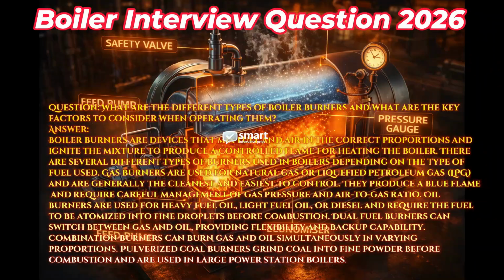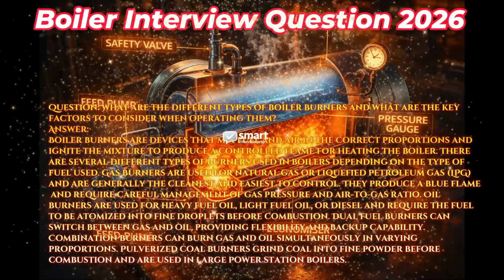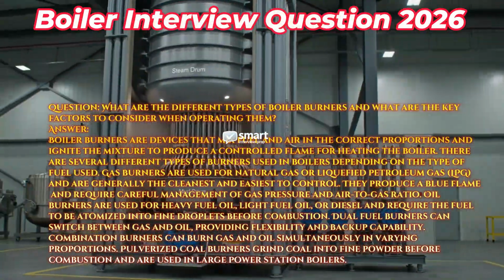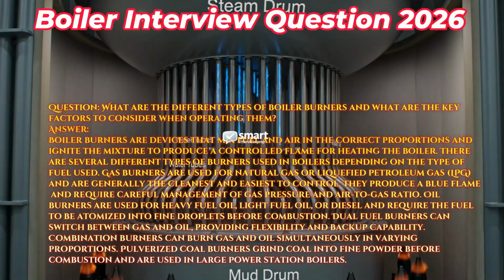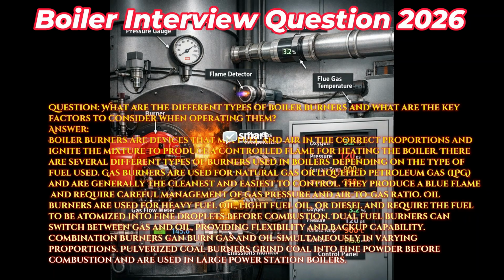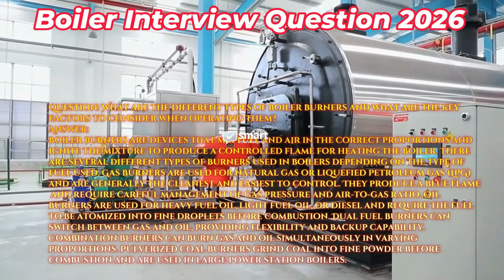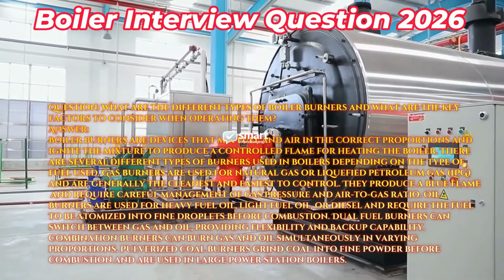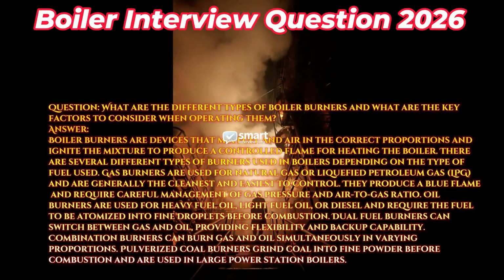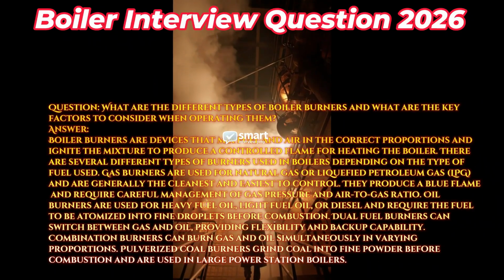Question. What are the different types of boiler burners and what are the key factors to consider when operating them? Answer. Boiler burners are devices that mix fuel and air in the correct proportions and ignite the mixture to produce a controlled flame for heating the boiler. There are several different types of burners used in boilers depending on the type of fuel used. Gas burners are used for natural gas or liquefied petroleum gas, LPG, and are generally the cleanest and easiest to control. They produce a blue flame and require careful management of gas pressure and air-to-gas ratio.